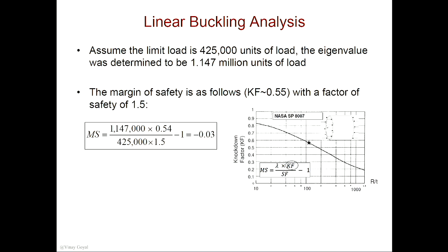And it makes sense because you're more likely to buckle into one of those shapes. So if I use those shapes and I put an amplitude to that shape of what I expect in my manufacturing process, perhaps now when I do my nonlinear analysis, I'll get the buckling load that will in fact precipitate the buckling, right? Because you need an imperfection to get it to go, right? And so we're trying to make that happen numerically instead of in an experiment.